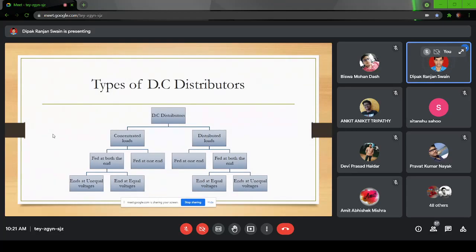So it is not possible to maintain equal voltage criteria always. Therefore, most of the time, it is feeding at unequal voltages. Let us say you get a voltage from NTPC Talcher to Bhubaneswar at, let us say, 33 kV or 66 kV, and another from the Sambalpur Hirakud power plant at 132 kV. Then both of them will be acting as feeders, but they will have different steps of stepping down to low voltages.